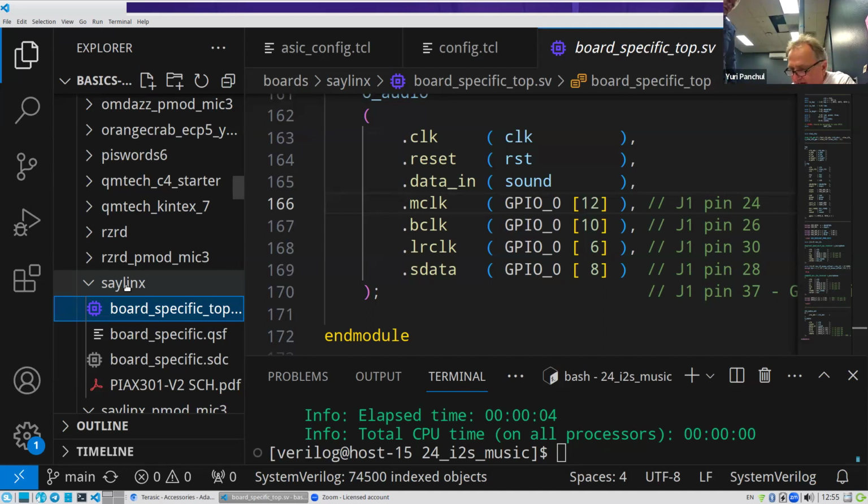It's two calculations. The problem is that the sequence here and the sequence in the code are a little bit different, because in code they are in a logical way: master clock, block clock, selector, data. But here they are in a different order. So first you get selector, then data, then block clock, and then master clock. See? So basically here they are in logical order, but on the header for this component they are in a different order.